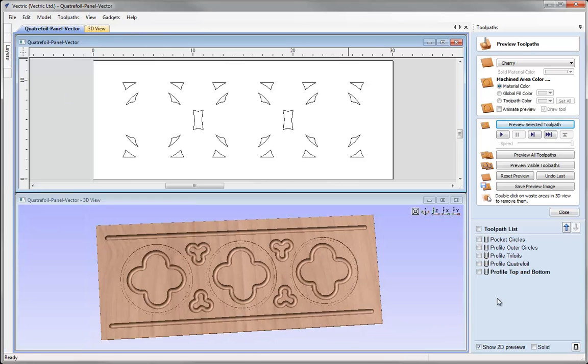And again, we've got a similar situation as we did with our quatrefoil and trifoil shapes, where some of our V-carving shapes are going to start at a lower depth than some of the other shapes. So some shapes are going to start from the top of the block, and some are actually going to start an 1/8 inch down in these circles here. So what we want to do is just highlight the inner circle shapes, as we'll V-carve those first. So to do that, we can simply drag a box around our inner circle shapes like this.